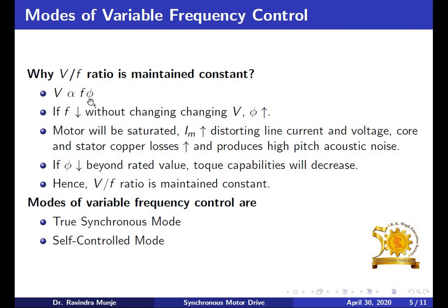Supply voltage is proportional to the product of frequency and flux. If frequency is decreased without changing the supply voltage, what will happen? Flux will increase. If the frequency is decreased in this expression without changing supply voltage, flux will increase. As a result, the motor will saturate.